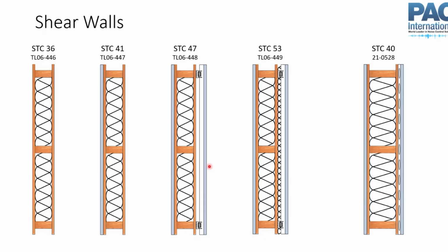And what this means is that we don't have this clear cavity path. So if you came in here and you put drywall just directly over this, right? Sorry, we don't have this clear separated structural path. So your sound hits this side, rigid connection from the drywall to your shear panel, rigid connection from the shear panel to the stud to shear panel to drywall, and the sound just comes right through here. So if you add another layer of drywall on this side, this rating only goes up a few more points, and you don't get anywhere near the code minimum.